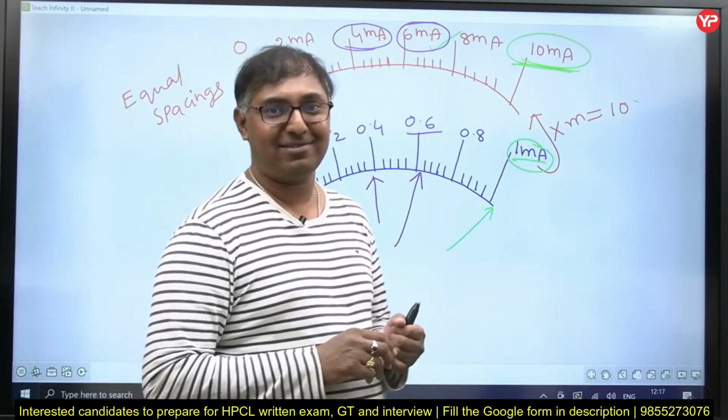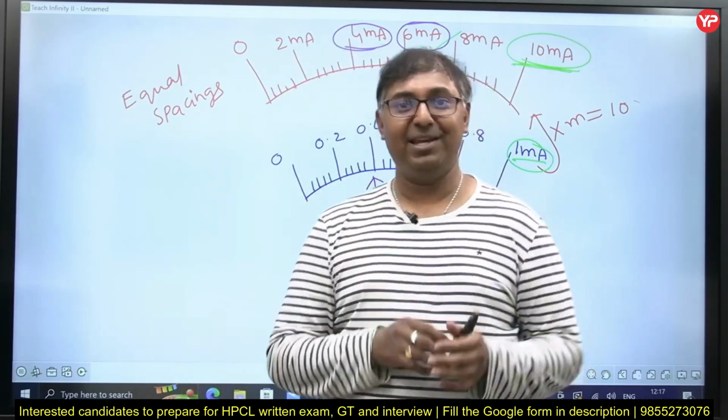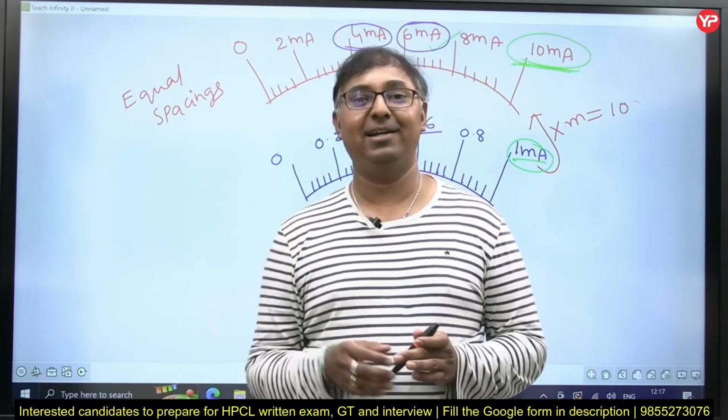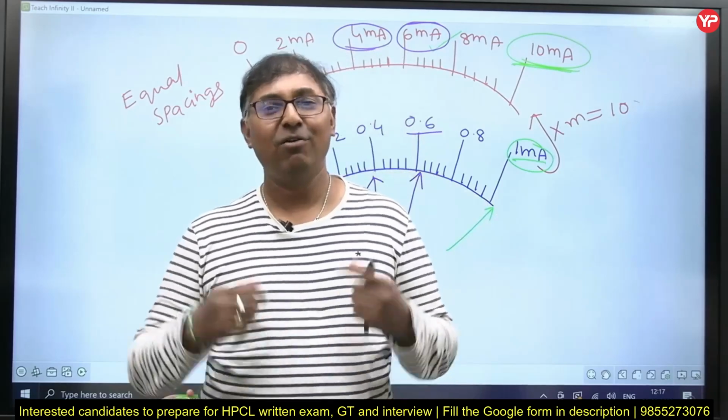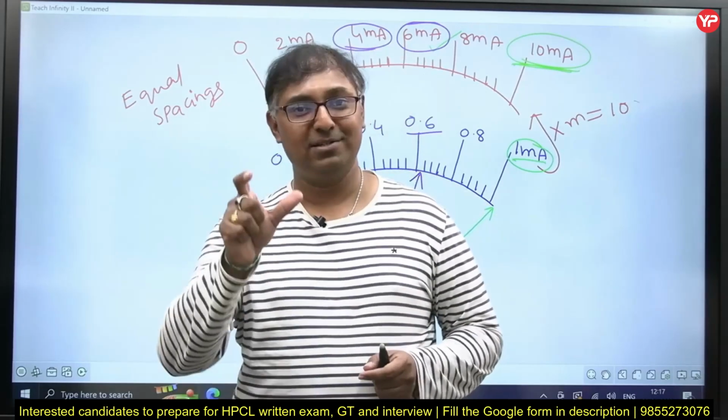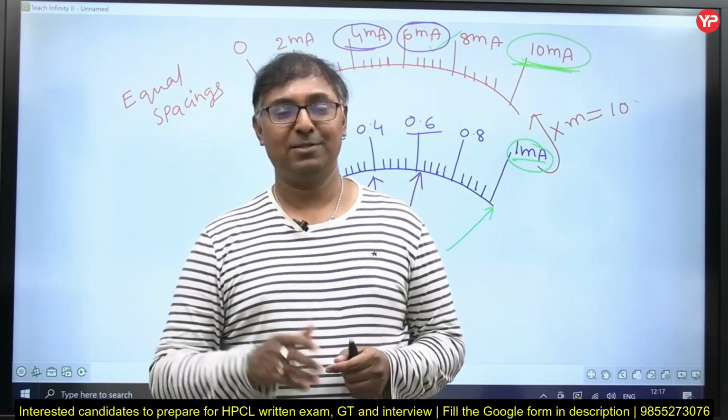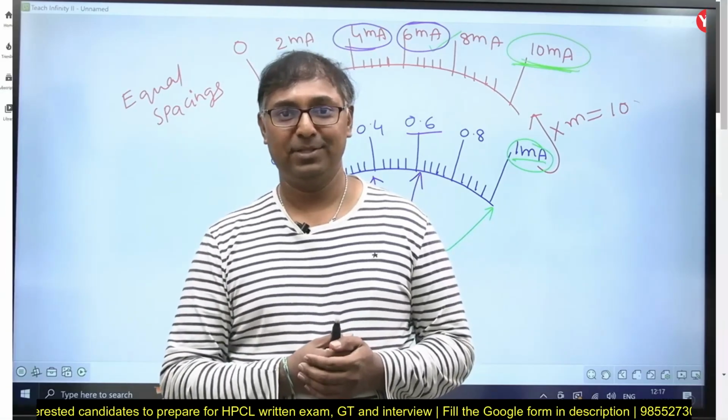If I summarize, the PMMC instrument can't allow high currents. The reason is that the springs are the current carrying conductors. Why do we have different ranges of instruments? This is the reason. The springs, that is the problem.